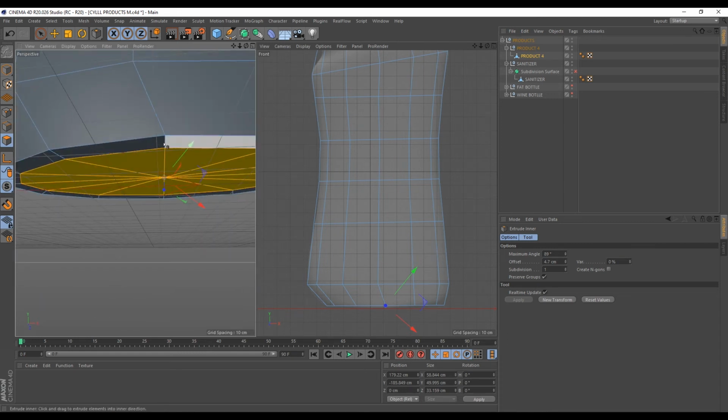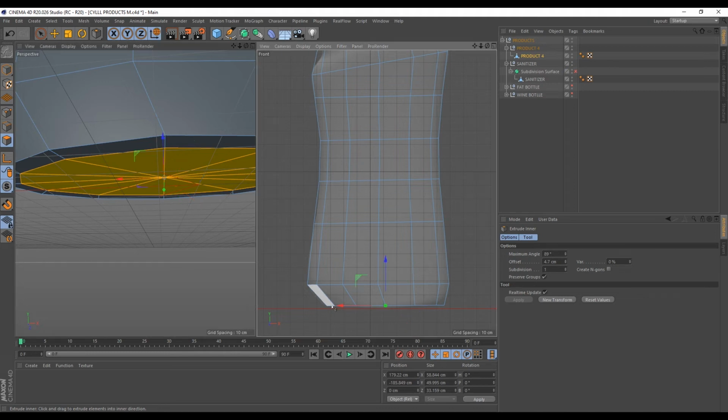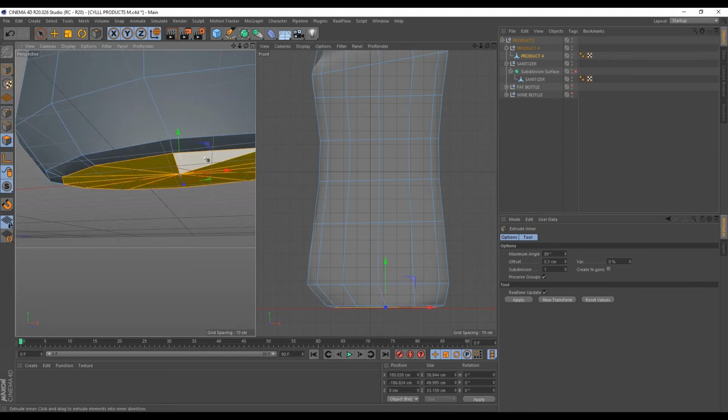So for the base here, once I insert the face, because we've been rotating our local coordinate, we can now switch back to our world coordinate because this is now a flat angle. So if I hit W, I'll change that back to my world coordinate. So I'll just create this base for myself this way.